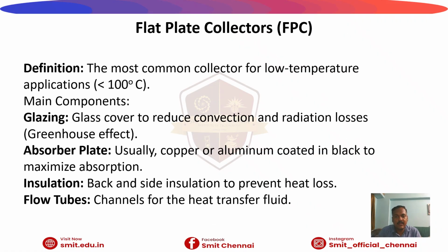Flat plate collectors are the most common collector for low temperature applications, less than 100 degrees Celsius. The main components are glazing, a glass cover to reduce the convection and radiation losses, and for the greenhouse effect. And the absorber plate, usually copper or aluminum coated in black for maximum absorption. And insulation at the backside, to prevent the absorbed heat energy from escaping. And flow tubes, channels of the heat transfer fluid. These carry the heat transfer fluid.